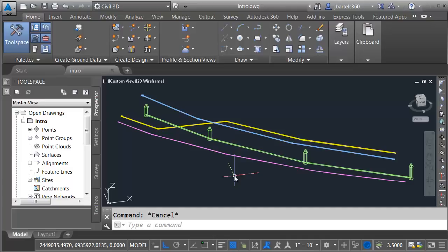Using survey data is best, but if your project is several miles long, it can take weeks to get all that information. So, in the early design phases of a project, some of the existing utilities may be modeled using GIS data. Some may be modeled from paper maps. Others may just be an educated guess. The challenge is that once you create the utility model, how do you remember which components have a survey grade location and which ones are a rough approximation?